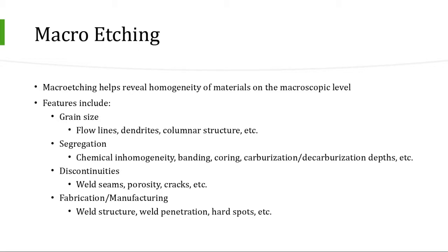Discontinuities of, let's say, for instance, weld seams. If you wanted to find a weld seam, and within that weld seam you have porosity. How about cracks? Determining where those cracks are emanating, ID, OD, are they in the heat affected zone, so forth.